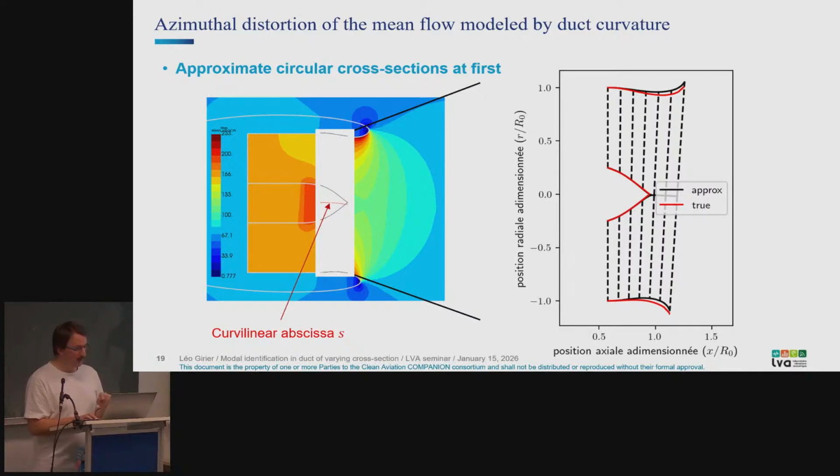So to tell you how I did that, I took basically the center line of the nacelle wall here, shown in a red line. And you can see that it does not follow the axis, but it bends downward, because the air inlet of an engine is actually a kind of bend downward to be at the right inclination when in flight. Well, doing so, I've rewritten the Helmholtz equation in curvilinear coordinates instead of Cartesian coordinates, still accounting for the variation of the cross section.